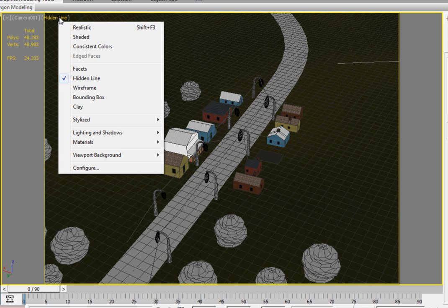This menu is broken down into several groups. The option you would choose depends on what style you would like to use for the viewport rendering. The current style is set to Hidden Line. Let's say you're giving a presentation and you want to change the style to something non-photorealistic. There are several non-photorealistic options you can choose from. These are located under the Stylize menu option.